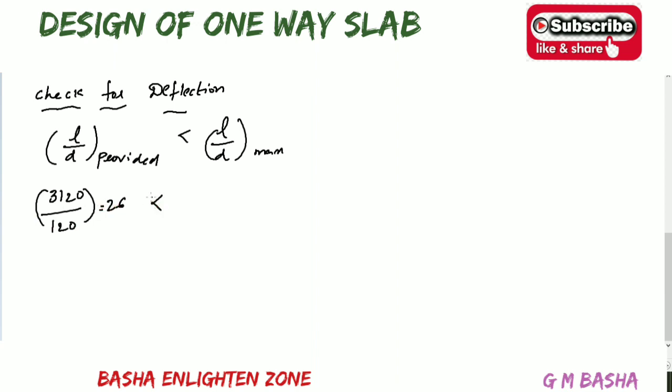And again check the condition. The value will be equal to 26 here, and check this condition whether the value obtained is higher than this one or not. And what about this L by D maximum? That value will be equal to the basic value, that is L by D basic, into its modification factor.